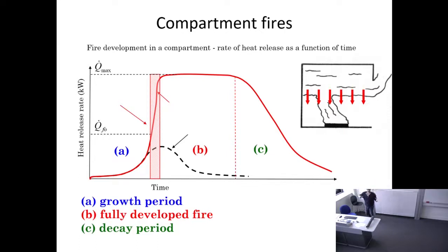So when it's burning flashover, the heat release rate will remain the same inside the compartment, not outside, inside the compartment, unless you open doors. You open doors, you open windows, the fire will grow because you have actually more ingress of oxygen. Or if you close, it will actually shrink, okay? And then it will have burnout, where it will run out of oxygen.